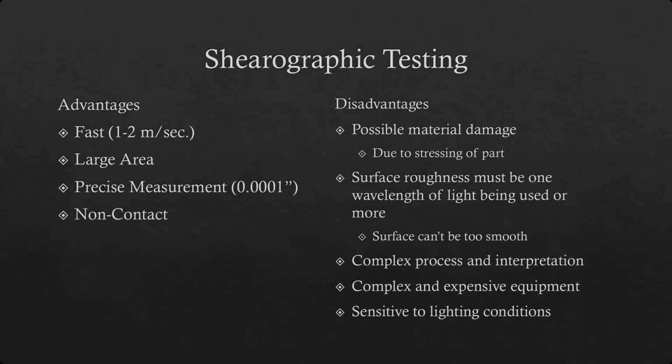Now, laser speckle interferometry, or shearography, can be sensitive to lighting conditions because it has to produce that speckling pattern on the surface. If you're in a very bright area, you won't get the darker areas. You won't get the dark spots on the surface. And there is some motion, again, just like holography, motion in the environment, vibration can be an issue. However, it's not quite as sensitive as holography. So again, shearography grew out of holography to overcome a few of those limitations that we had with the older technology.